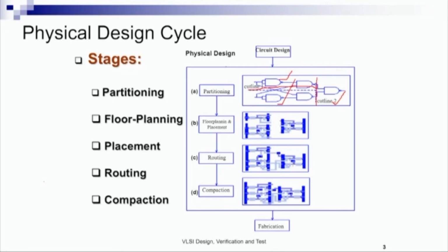In the routing phase, what we do is we obtain for each wire connecting the blocks a set of areas through which it will be interconnected. So, we have areas between the blocks. The vacant spaces between the blocks will be divided into structures called channels and switch boxes, and we have to route each wire, each interconnection between every two blocks through these vacant spaces, and also over the top of the blocks, and connect these blocks. This is done in the routing phase.